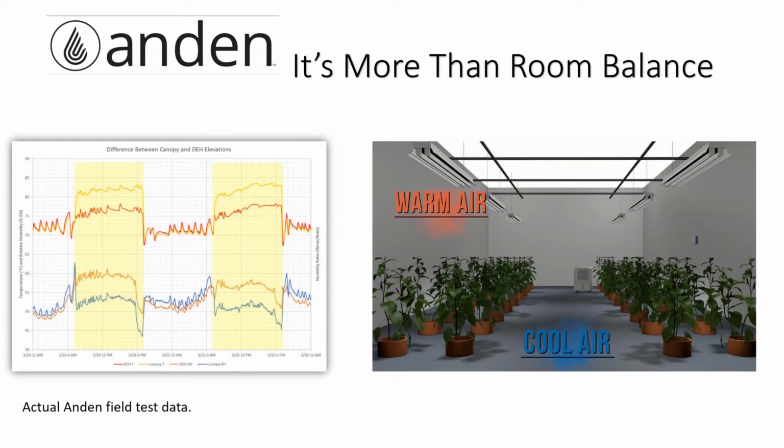Perfect example, I was with an LP in Ontario just a couple of weeks ago, and I'm sitting inside of their room, and he's showing me how wildly his room is balanced compared to the average grower. He has chillers in this room, he has dehumidifiers in this room, he has steam humidifiers in this room. And he has different lighting controls in this room. So we have steam humidifiers, dehumidifiers, chillers, everything in order to balance the room. The reason was the room and where the sensors and everything were for the room were not what was controlling how that room felt.